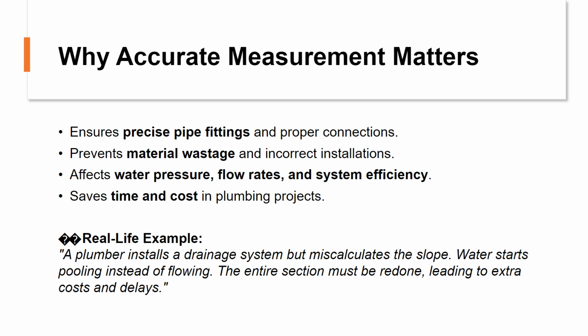Real-life example. A plumber installs a drainage system but miscalculates the slope. Water starts pooling instead of flowing. The entire section must be redone, leading to extra costs and delays.